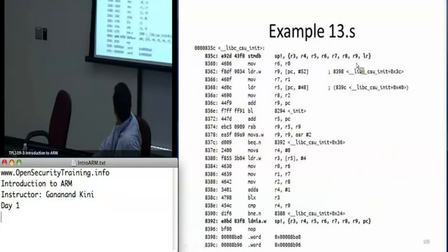So here's an example of a function prolog and epilogue, is what it's called. The prolog actually stores the registers that are going to be messed with in this method onto the stack. So you see they're using STMDB. And then they actually do their work, mess up all the registers, and then they want to load them back. So they use LDMIA to load them back. So when you specify here, they're using the link register to store the link register on the stack. And once they're done, they actually put it back into PC directly. And so that causes the branch to occur.